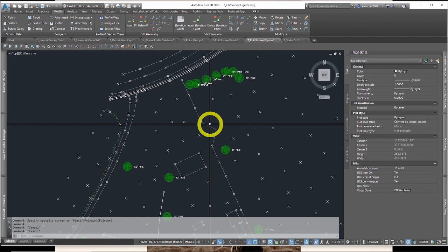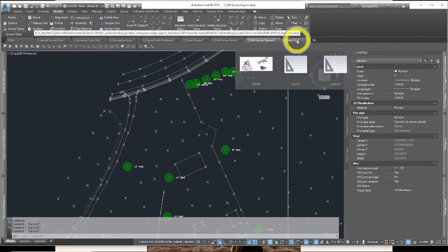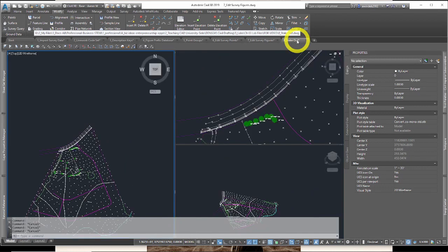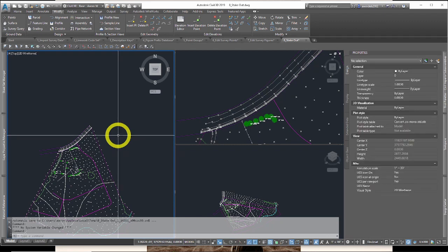Now, the last part of this chapter, we're going to create some additional survey points called COGO points, and occasionally you need to create your own points to establish, let's say, key locations in a drawing. I'm going to go to the stakeout drawing while I'm talking about this and let it open. What I mean by that is you want to show specific locations, let's say, of proposed curb or test borings, or proposed property corners that need to be found.